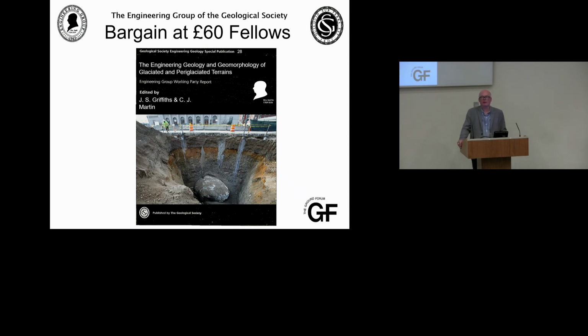Yeah, that again was the key message, that you had this highly variable terrain that then had this blanket of infill over it. And what was the infill? What was the geotechnical variability? And again, if you're getting differential settlement, you get differential permeability. You're getting differential pathways if you're looking at contaminant models, for example. And that was a key message, that you didn't have uniformity in the terrain at all. You had this legacy of valley systems, of tunnel valleys, of infill, of hollows, depending on where you were, linking through again to the bedrock: if you had a lithology, how did that lithology respond to those climatic conditions? How did it respond to being glaciated? How did it respond to being periglaciated?